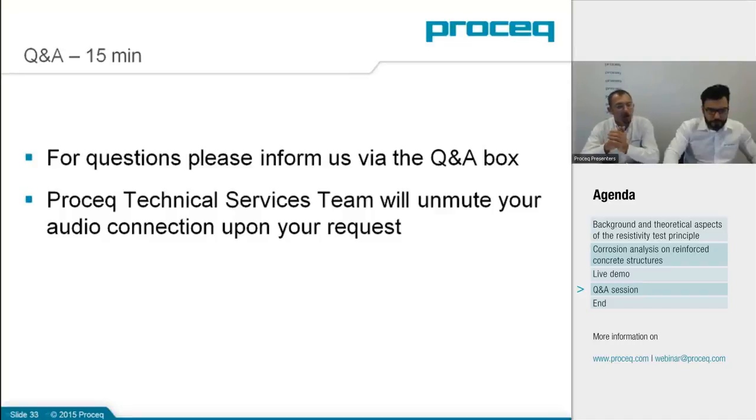So our instrument uses 40 Hertz alternating current. We impose a current which, depending on the two ranges available, we force 200 microamperes or 50 microamperes. Those are the parameters fixed on the instrument.